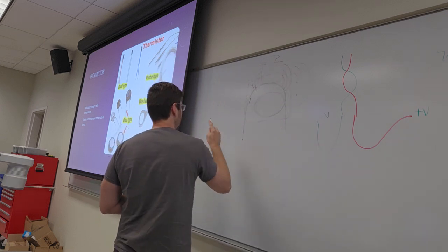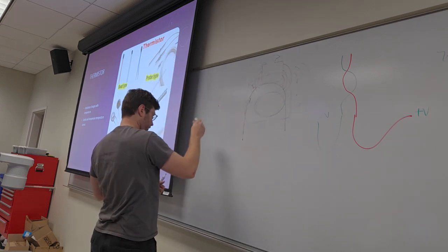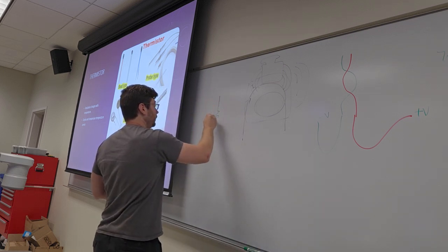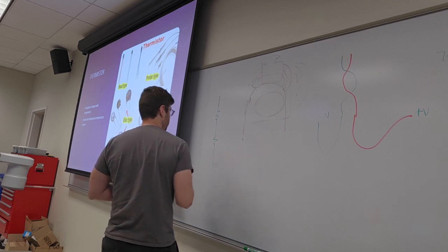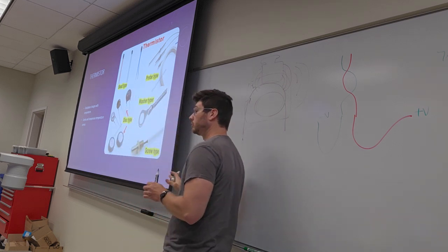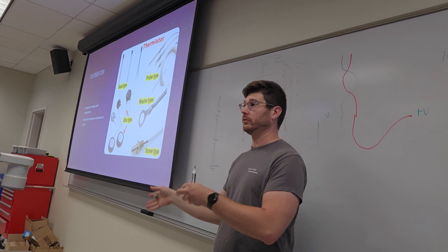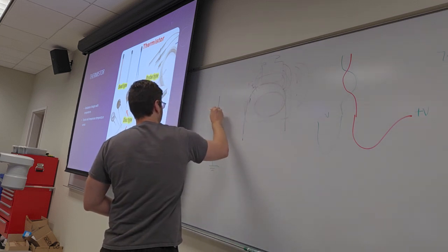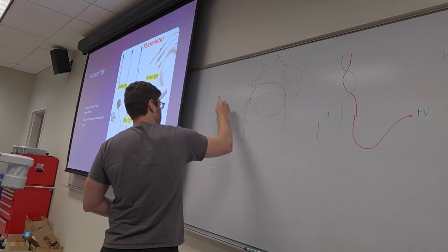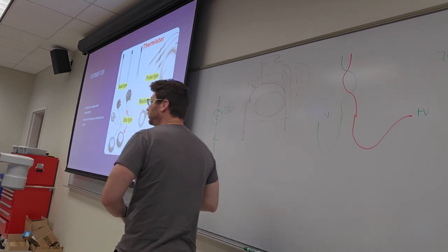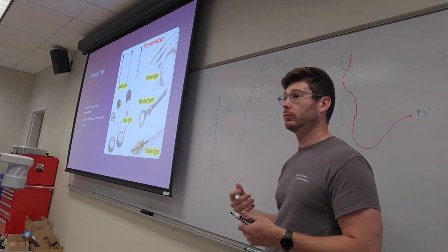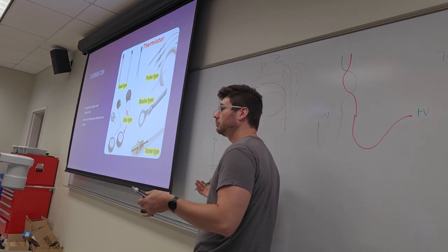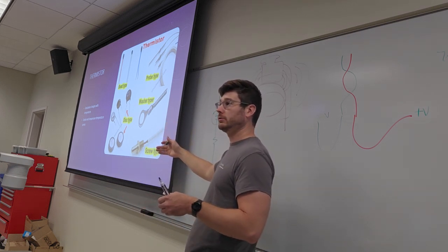A thermistor is essentially a resistor. A good resistor doesn't change resistance with temperature, right? It's more or less stable. A resistor in Hawaii is the same resistance as it is in Alaska. A thermistor is made bad on purpose so that it does change resistance with temperature. It does so in a very controlled and understood way, so that when this resistance changes by a kilo ohm, we know we have changed by so many degrees.